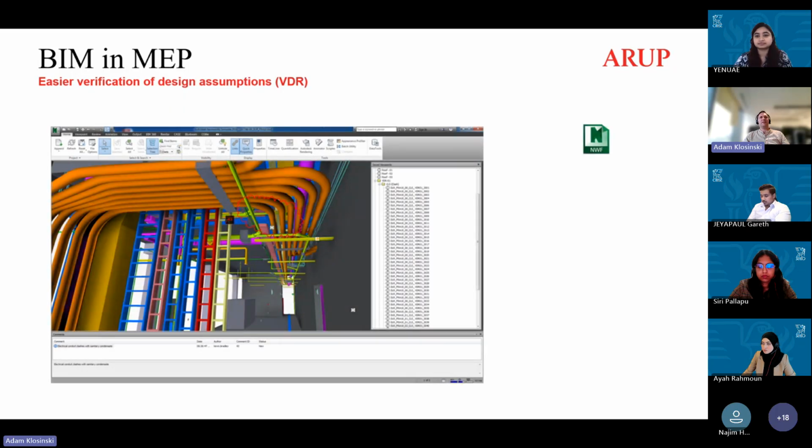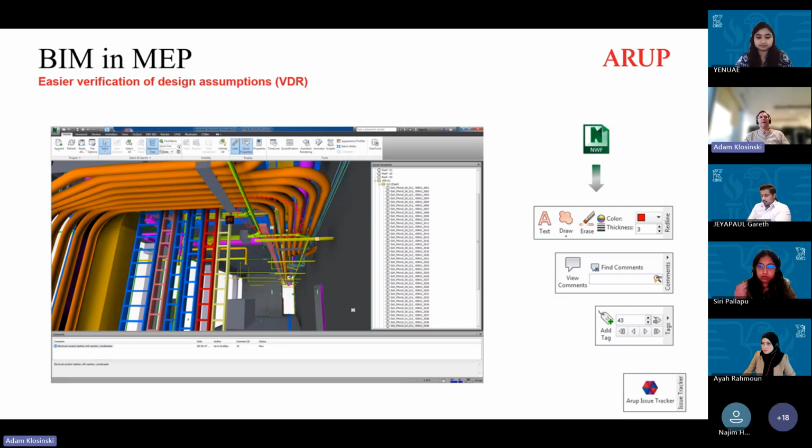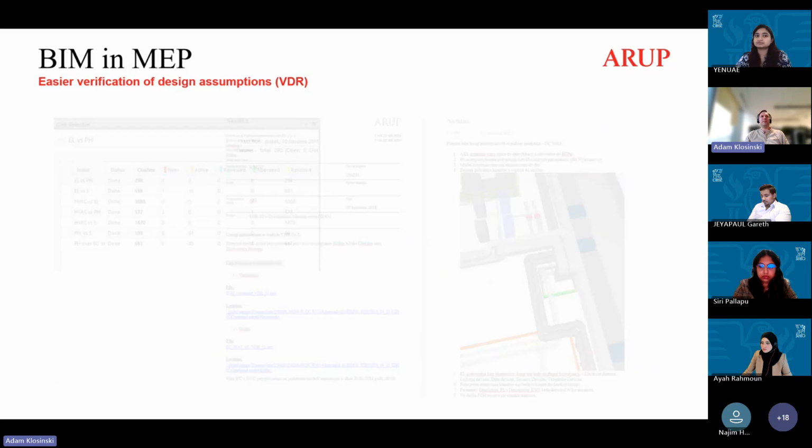And later on, once we've got the insight, we are also able to produce markups, and as I have said, instead of creating markups on PDFs, we can use dedicated tools or the BCF format. This is the BIM Collaboration Format, and based on this, the efficiency between the design intent and how it's going to be implemented in the model is definitely better than providing this on PDFs.